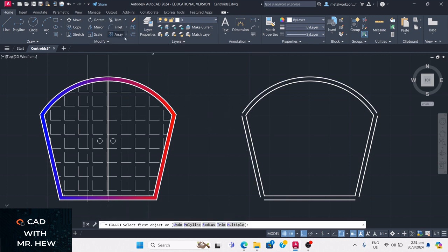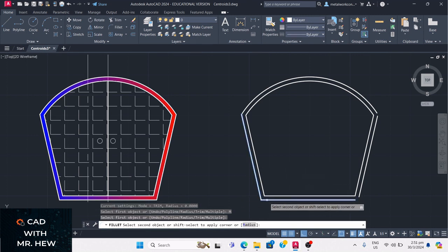So we go fillet. I click here, there. Now the command went away. So I'm gonna show you how you can do multiple fillets. So we press enter to get back the last command. I'm gonna press multiple. So we click this line, we click this line, we click this line, we click this line. There's a fillet automatically closing for us. Click this line, enter.